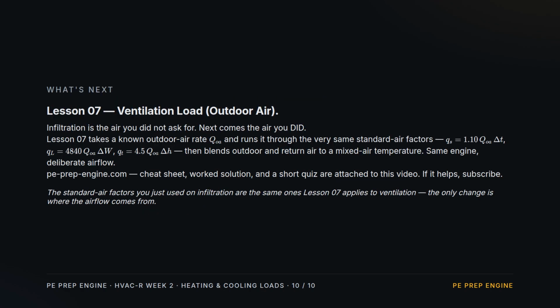Next up, Lesson 7. The ventilation load. Same standard air factors, but now the airflow is deliberate. A known outdoor air rate you push through the system, plus the mixed air temperature when outdoor and return air blend.